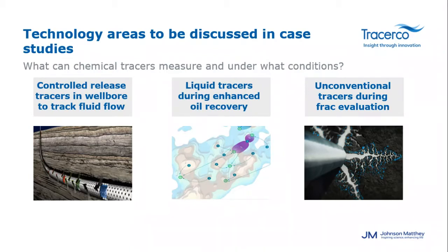Controlled release tracers are attached to the completion downhole for zonal contribution for years or the lifetime of the well. The lifespan of the tracers' responses is dependent on the mass that can be applied and the flow rates of the intended phase. Second are liquid tracers applied during injection to understand the relationships and communication to the producer for enhanced oil recovery. These tracers can provide valuable data on the connection between the wells, such as insight into the effectiveness of injection programs. They are highly specialized and can even be designed to provide residual oil measurements.